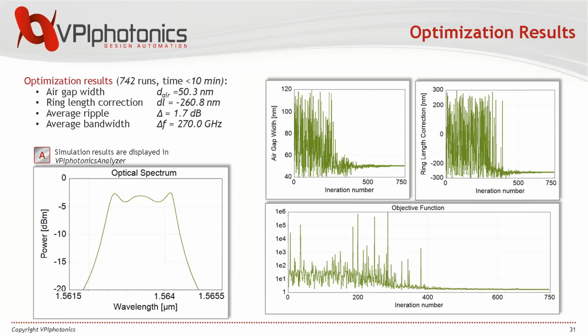As one can see, the optimum transfer function we found is not absolutely flat, so we cannot fully eliminate ripples, which was possible for ideal models a few slides before. These features are dictated by intrinsic properties of the transfer function of our directional couplers, and we cannot, in reality, get rid of them, at least for this design we chose.